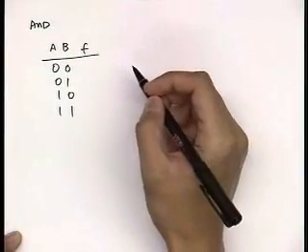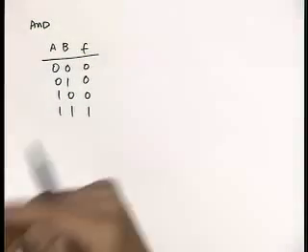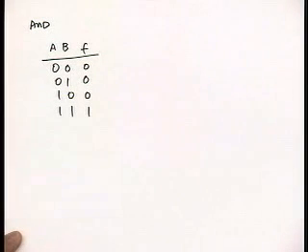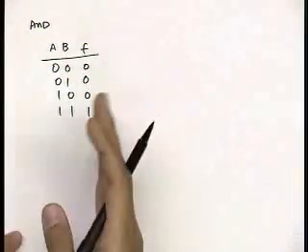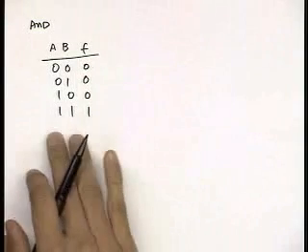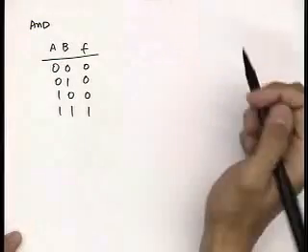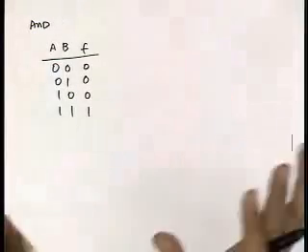So what's the truth table? It should be 0, 0, 0, 1. Now, notice that I can always express f as a function of one of the input variables. I think they call that variable entered mapping if you do that type of design.